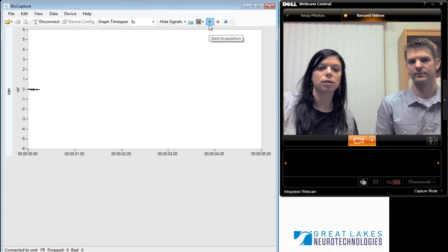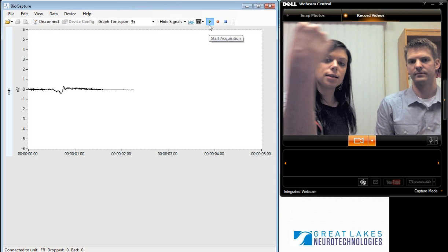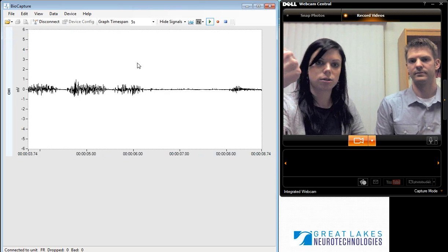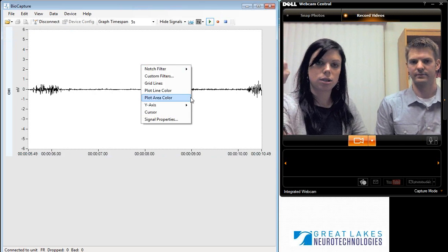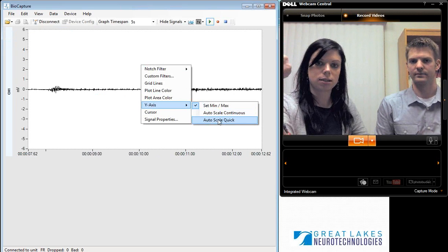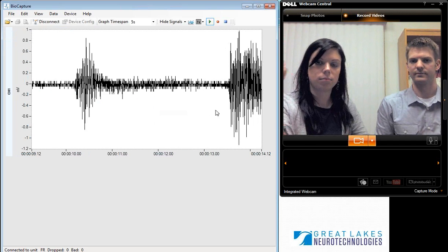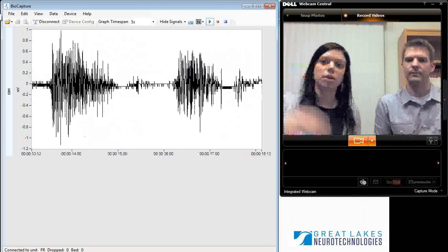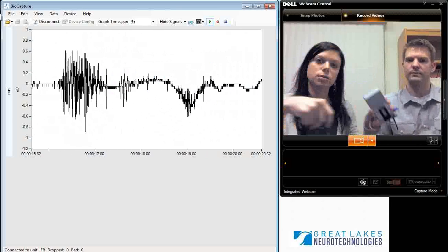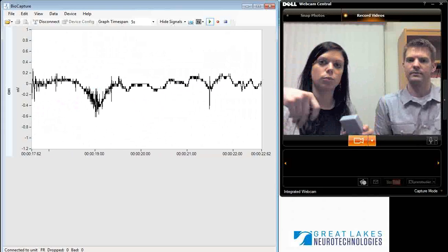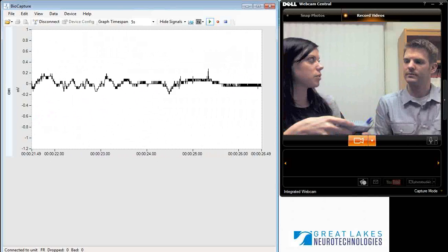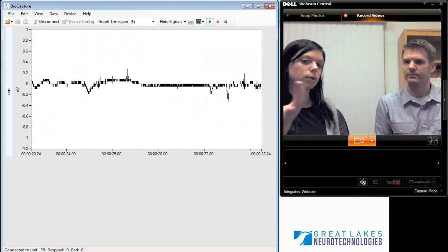So you can see that as I flex my arm here, you do get that increase in amplitude. And what I'll do first actually is just change the y-axis scale of this to get a little bit better picture of the EMG. So one of the things that you might see that's occurring is as I move these electrode leads around, the signal's getting somewhat distorted. And Eric had kind of talked thoroughly about different sources of noise. So what's something that we could do in this instance?